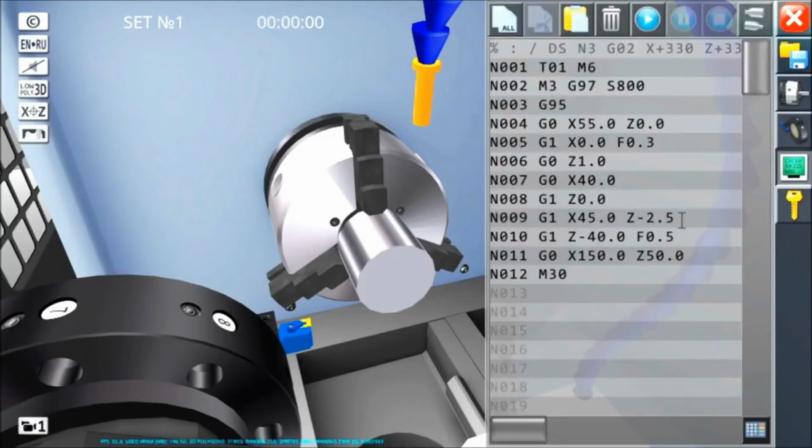The reaching from X40 to Z0 of the 2 coordinates will be done according to a straight line, okay, so if we need an inclined angle 30 degrees or 45 degrees we'll put different coordinates. Direct programming will help us, but we'll see that later.